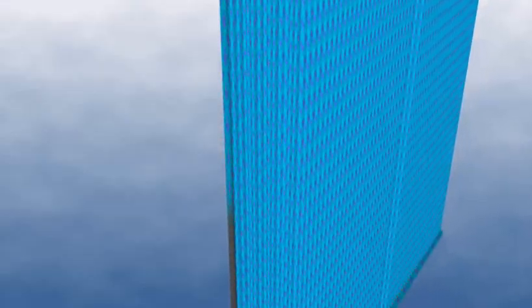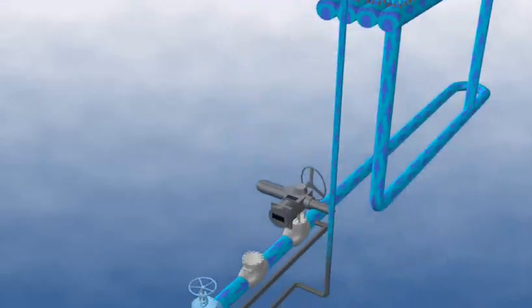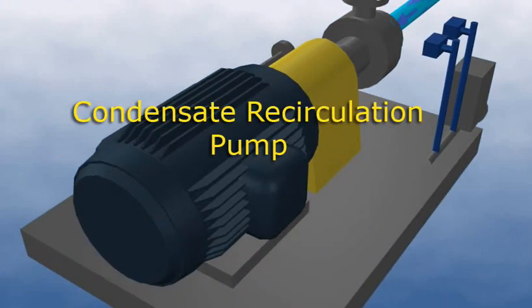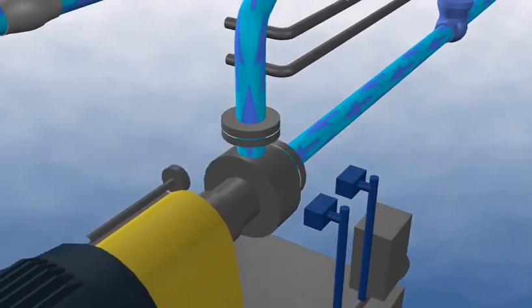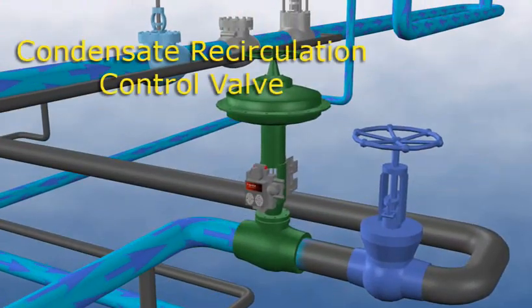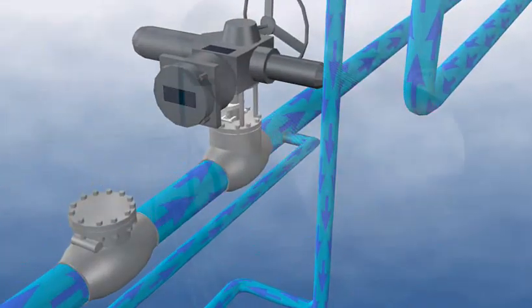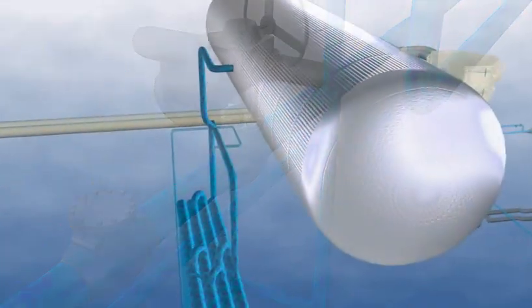Condensate recirculation is performed when gas side and water side temperatures are low enough to allow accumulation of moisture or sweating on the gas side surface of the LP economizer tubing. Such sweating can lead to corrosion and fouling of the tube fins, resulting in a loss of heat transfer efficiency.